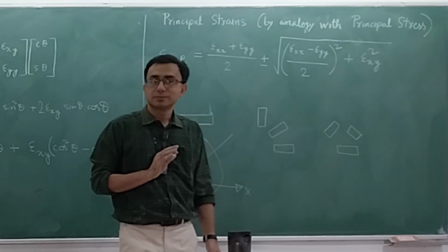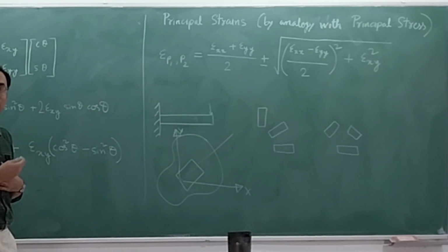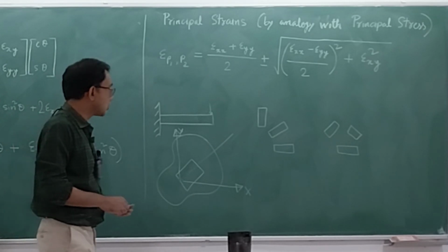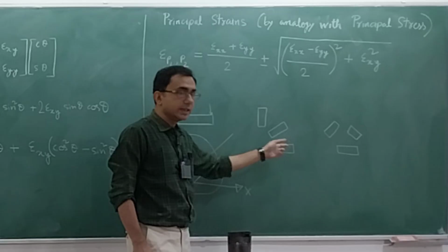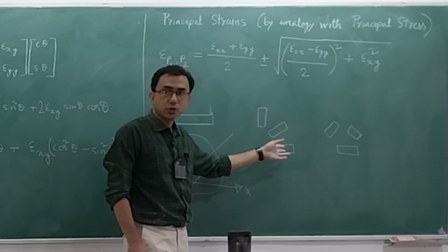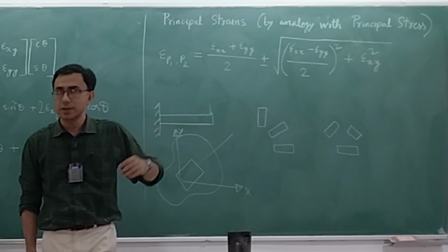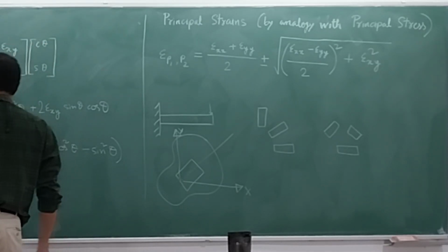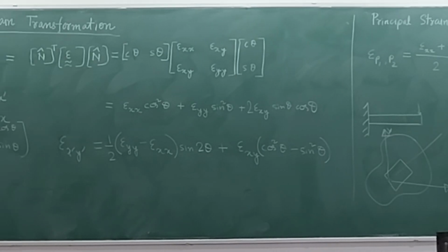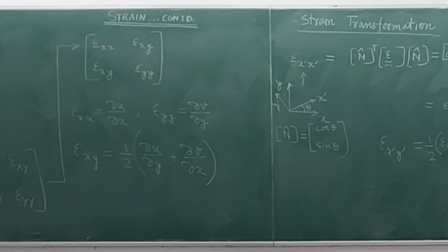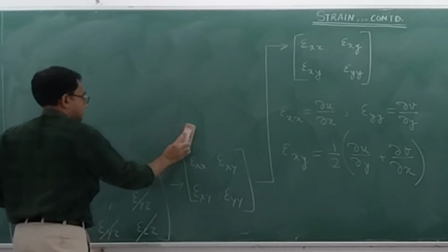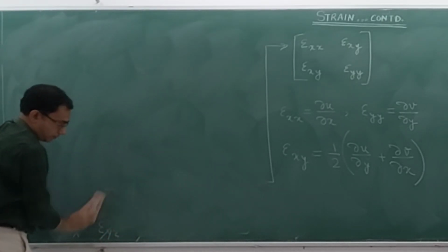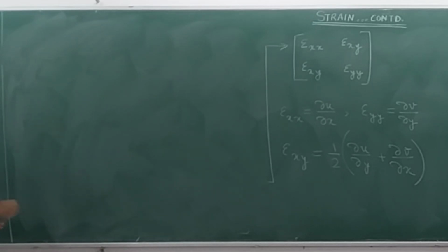So what is going on? Mathematically, what is going on? Suddenly we have not shifted gears and moved on to a lab course. So what we are going to do is just to write the expression of each of these strain gauges, the normal strains along those directions in terms of the epsilon xx, epsilon yy, and epsilon xy. And by reverse engineering we'll be able to find out the things. So it is like this. These combinations of strain gauges are referred to as strain rosette.